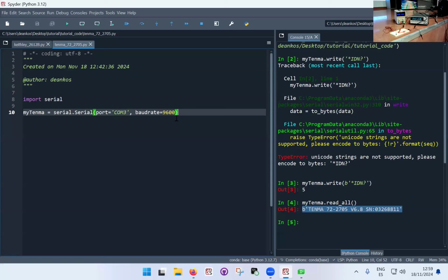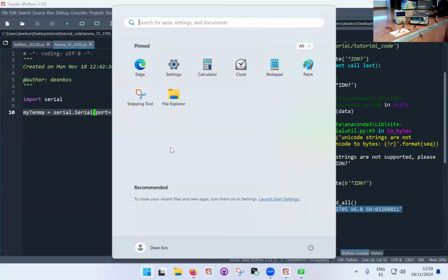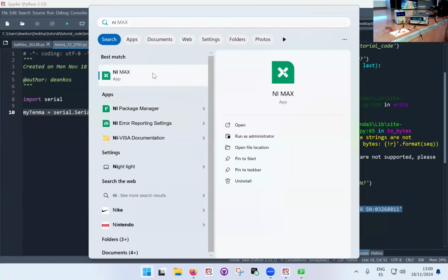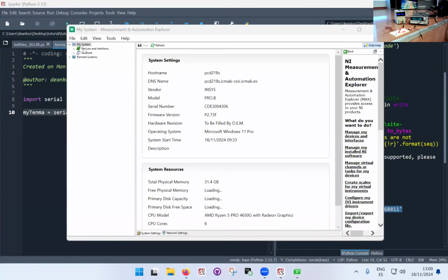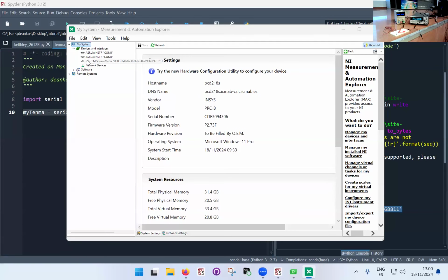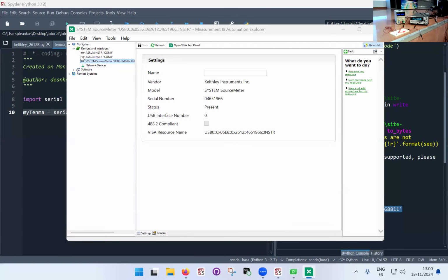I mean, clearly you see that in the NI MAX, it detected the instrument as a serial instrument, and so the icon I think is kind of a hint of the type of instrument that you've got. But let's see, license interfaces. I mean, it tells you what kind of port you've got connected. So I would assume that yes, you would connect it with a serial port, and it should use the Visa libraries. You can quickly check it, but just try it.